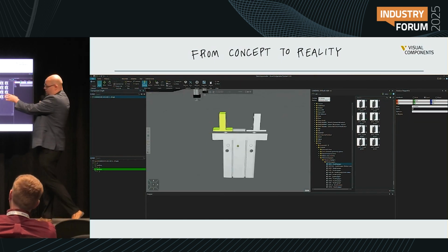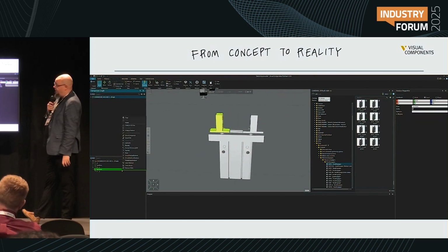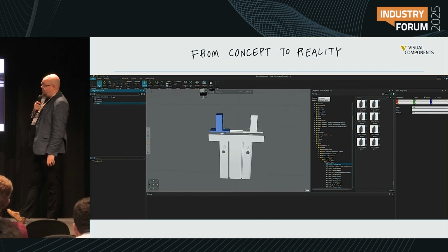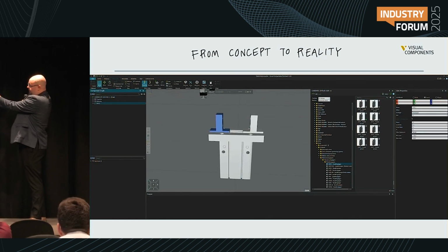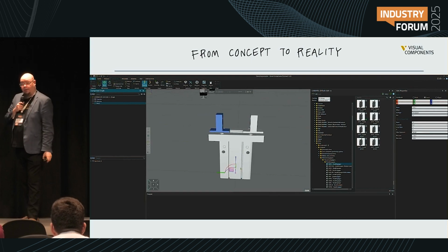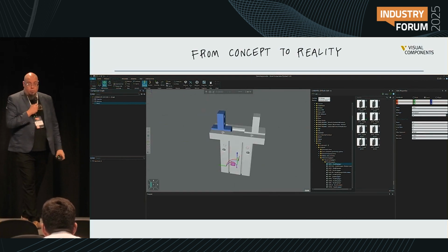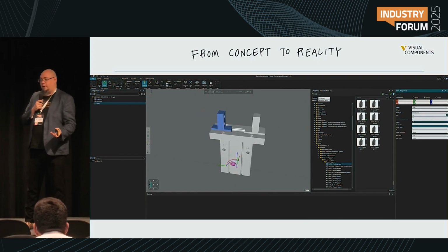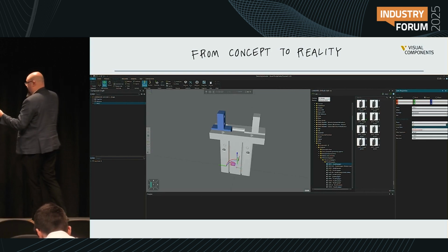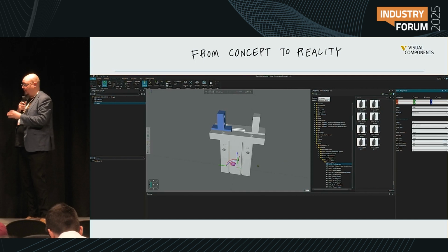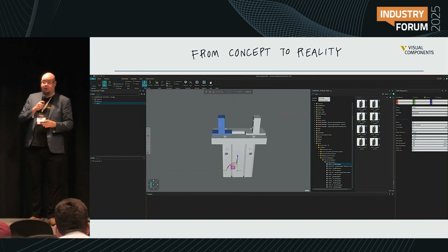in this case, we will select one of the fingers, we separate it to a different moving node, and then we define that, okay, it is a moving axis, it is run with a servo, it has its own axes of freedom, it has a speed, acceleration, deceleration, lag, settle time.